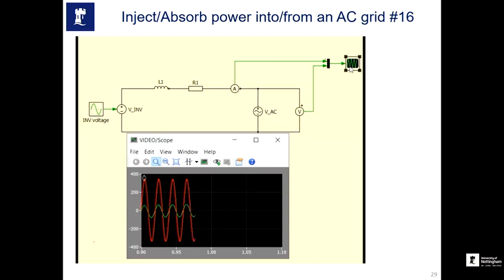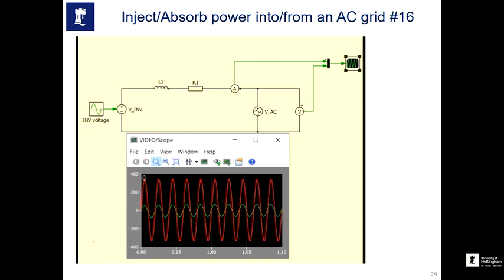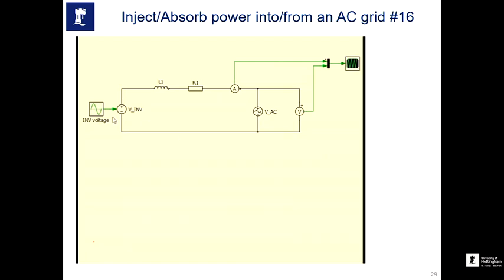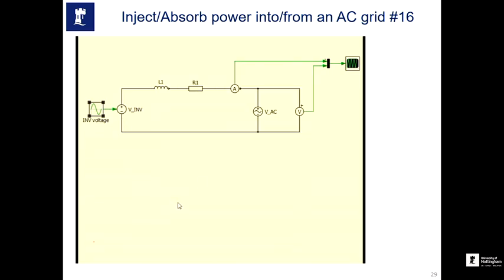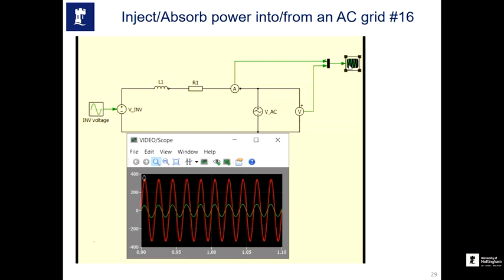Now you can see the current, which is in phase with the voltage, which means you have real power in the system, but no reactive power. Okay, because as you remember, the angle, the phase shift controls the real power. The magnitude, now the phase shift is negative. You'll see the real power will change.